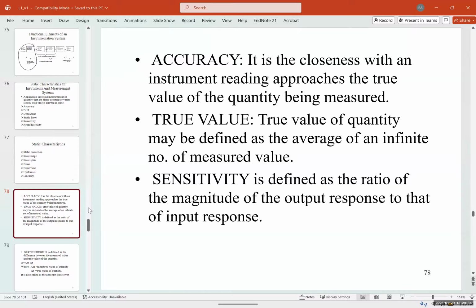And then we have a sensor, like an ultrasound sensor, that measures the water in the tank. And that ultrasound sensor shows us 1.1 gallon. So we know that the actual volume of water is 1 gallon, and the measured value is 1.1. So the accuracy is within 0.1 of that measurement.